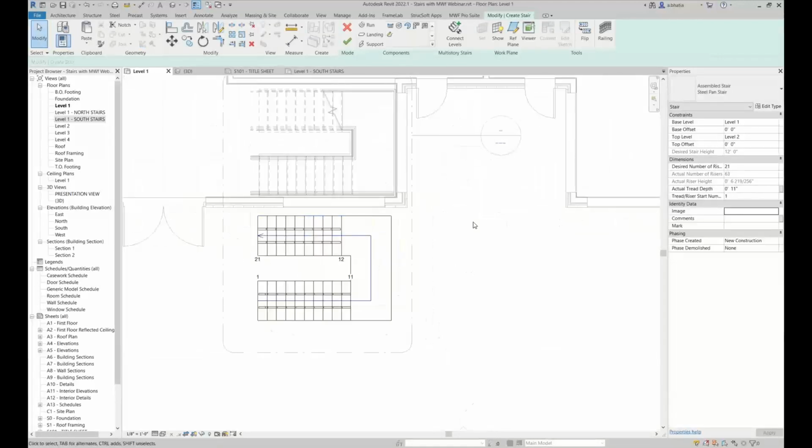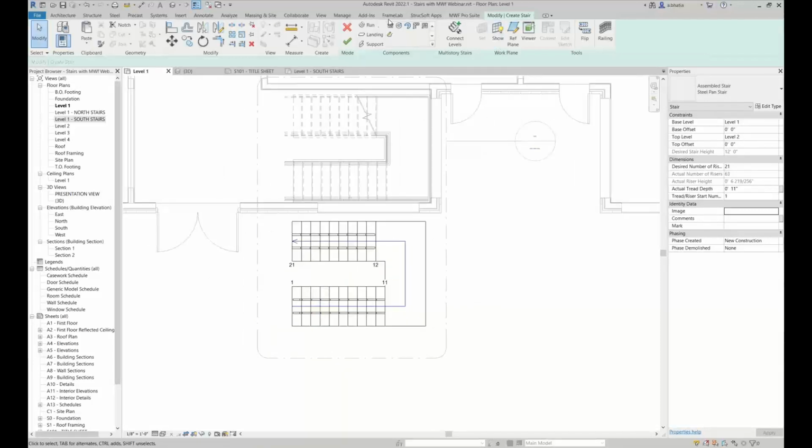So typically the rest place is at, I think it's an 8 foot, 6 foot or 8 foot minimum requirement. So once the traveled distance exceeds, I think 14 steps or 13 steps, you have to place a landing, basically. So for commercial places, this is the requirement. So yeah, that's basically it. That's why we have a landing there. Those are your different types of stairs that you can create.